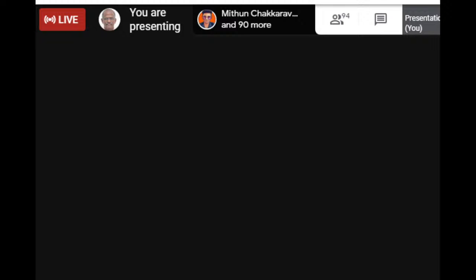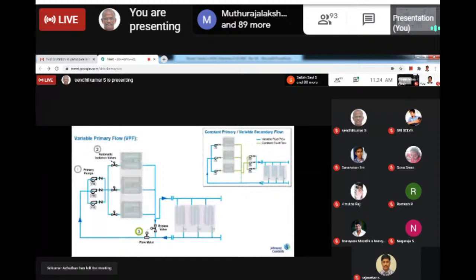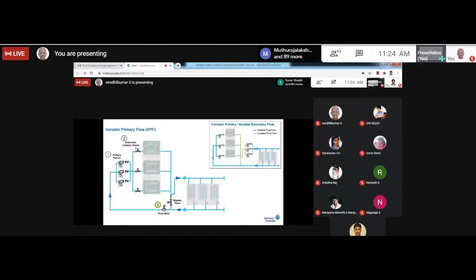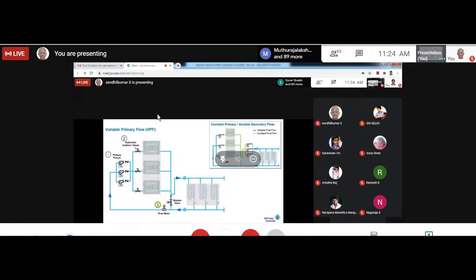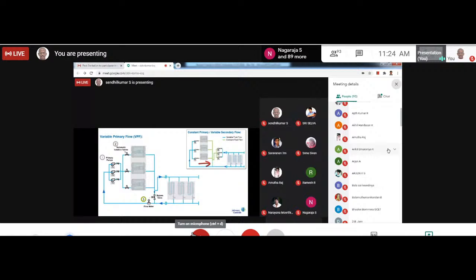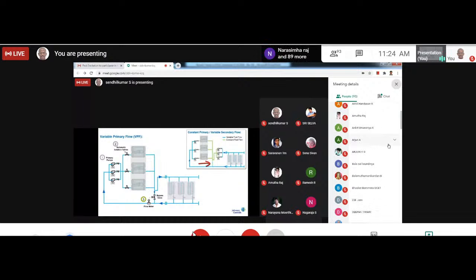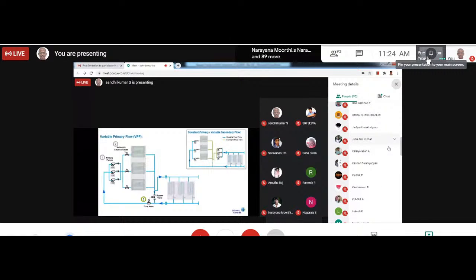This approach is compared to a primary-secondary system, where again there is a common pipe shown, but no flow regulation, meaning fluid is able to flow in either direction to balance the system. However, the unwritten rule with this design is that the primary flow should always be equal to or greater than the secondary flow for optimal performance. Therefore, the flow would follow the same path as a VPF system.